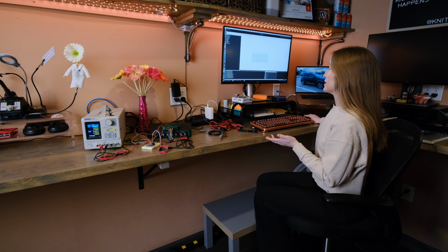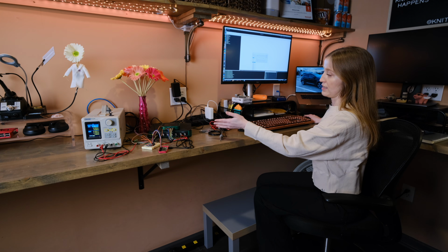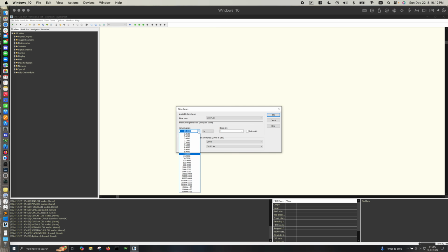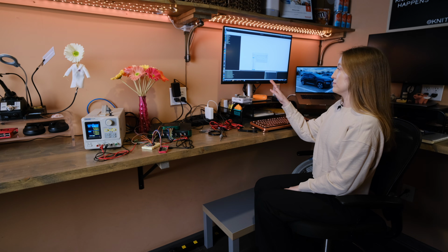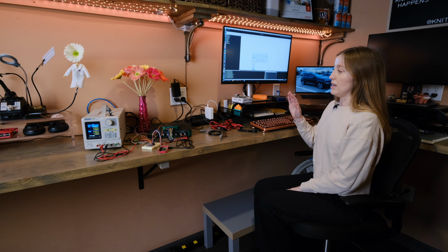So if I'm working with the Analog Discovery 3 or the ADP3450, and I choose a sampling rate of, say, the max 5 gigahertz here, which DASYLab can support, even though I know individually these guys can go a little bit higher, that means the measurement sampling rate can't be any higher than that.